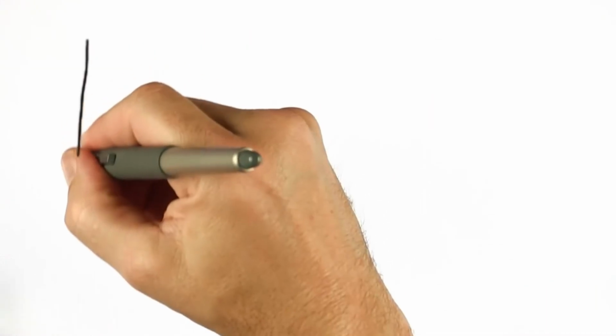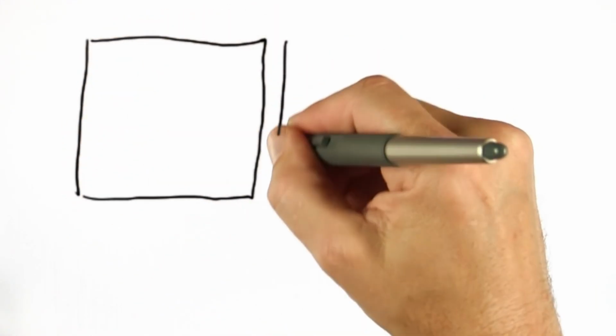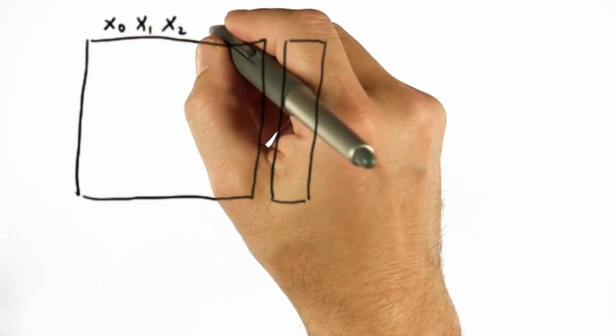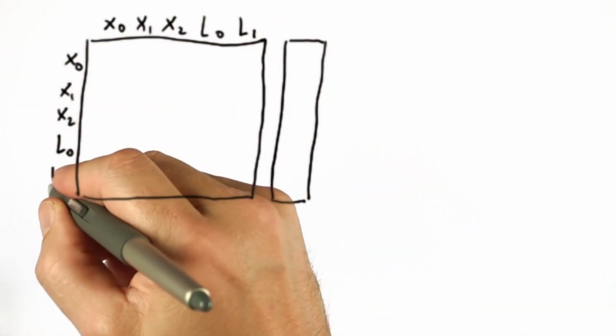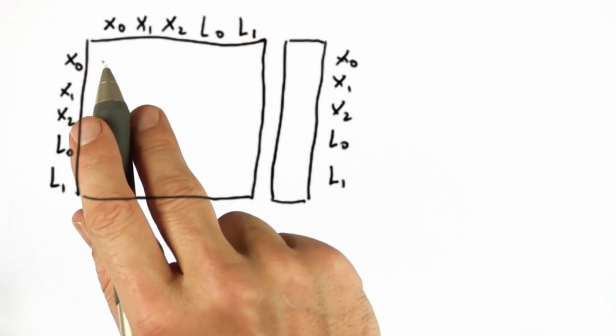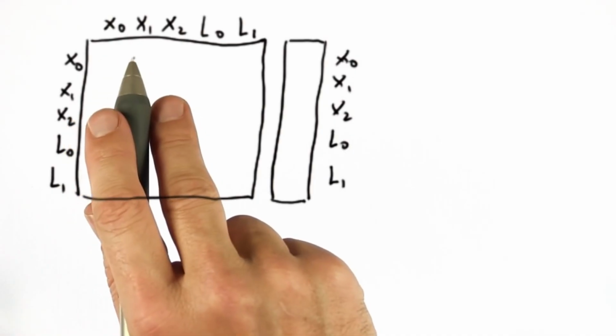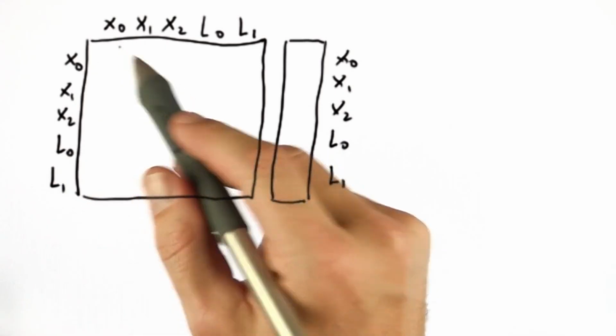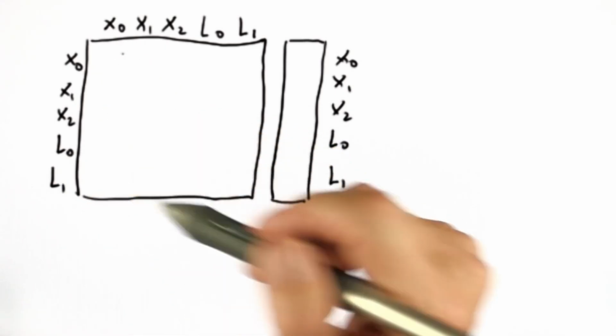What we do is we make a matrix and also a vector, and we label the matrix, which is quadratic, with all the poses and all the landmarks. And here we assume the landmarks are distinguishable. And every time we make an observation, say between two poses, they become little additions locally in the 4 elements in the matrix defined over those poses.